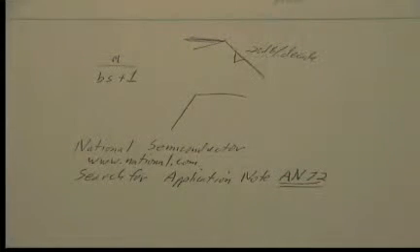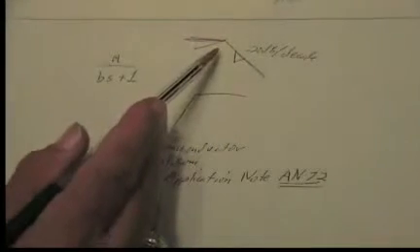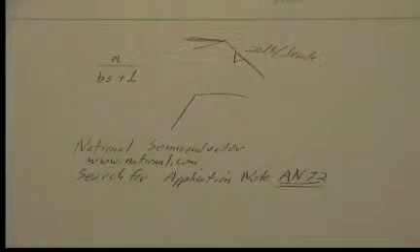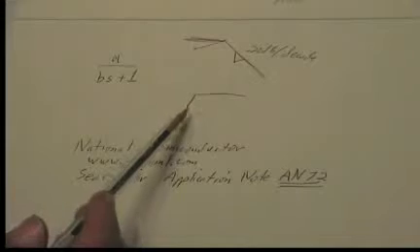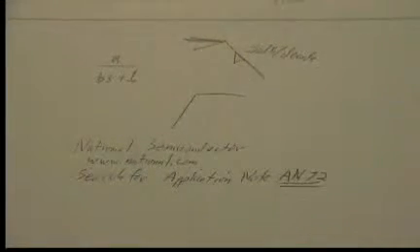is application note 72. It's written a long time ago, but it's got a whole bunch of basic op-amp circuits in it, and for a number of them, enough analysis that it tells you how to design, how to pick resistance values and stuff like that. In particular, it has a two-pole low-pass filter, which is very nice to give you all the design equations for it. They also give you a circuit for a two-pole high-pass filter. By cascading these together, you can start to approximate the type of behavior that you're looking for in your particular circuit.